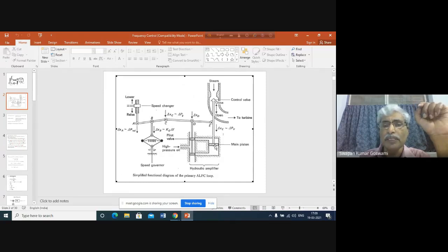So what will be happening? Oil from this portion, from this chamber, will drain out through these spaces. High pressure oil will maintain its pressure here. As a result, from this chamber, oil will enter into this and give a pressure. Now the piston will easily come down because the oil below this piston is going out. And at the same time, high pressure oil from here will enter into this chamber and finally into this chamber.